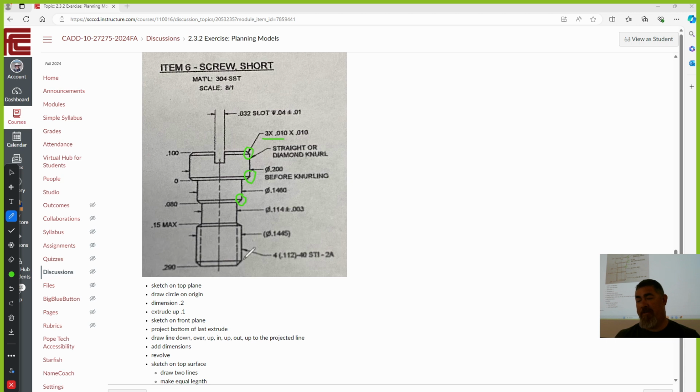So a chamfer is the thread depth. You can see this is the depth of the thread, and the chamfer is the same size. We want to chamfer the same depth as the thread is, so that way the thread will start nicely. Top and bottom. And then this one's there, and this one right here, it's the same depth, but it's just not as wide, so it's not a 45. But this one really doesn't matter because it's just giving some relief. That back side of that thread doesn't matter. We're not going to thread stuff from that side. It's just giving it so it's not a sharp corner there.